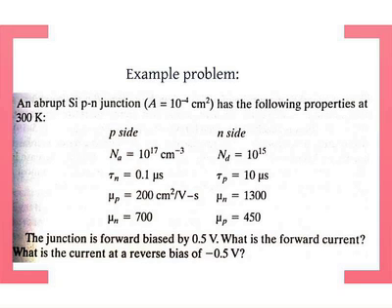And n is what? This is the majority carrier concentration in the n-type material. What is it? Someone said it actually. Would it be ND? Yeah. Right. Because it is heavily doped. You can just make the assumption, right? That's okay, right? That should be pretty obvious. Okay. So you know this now.